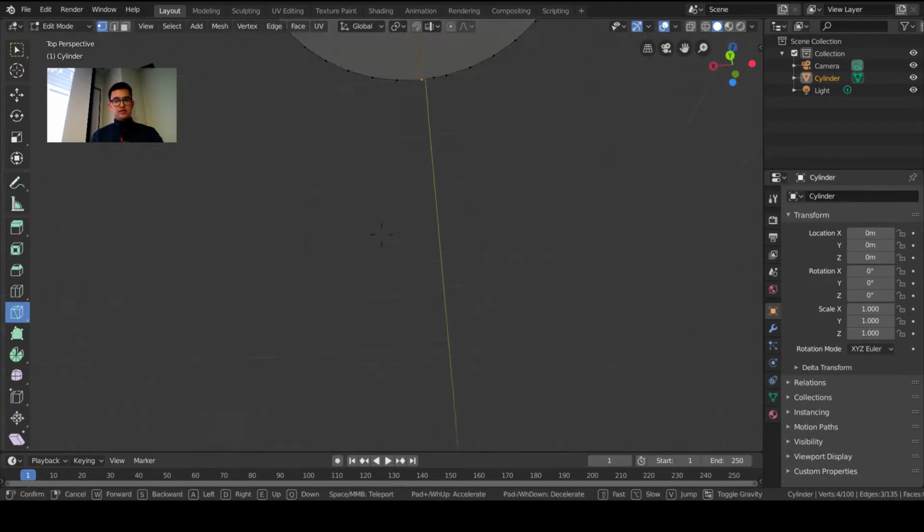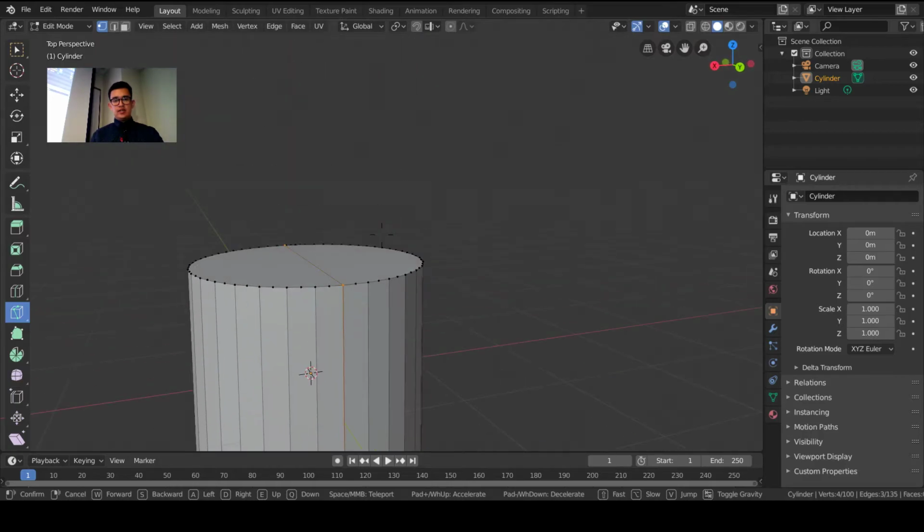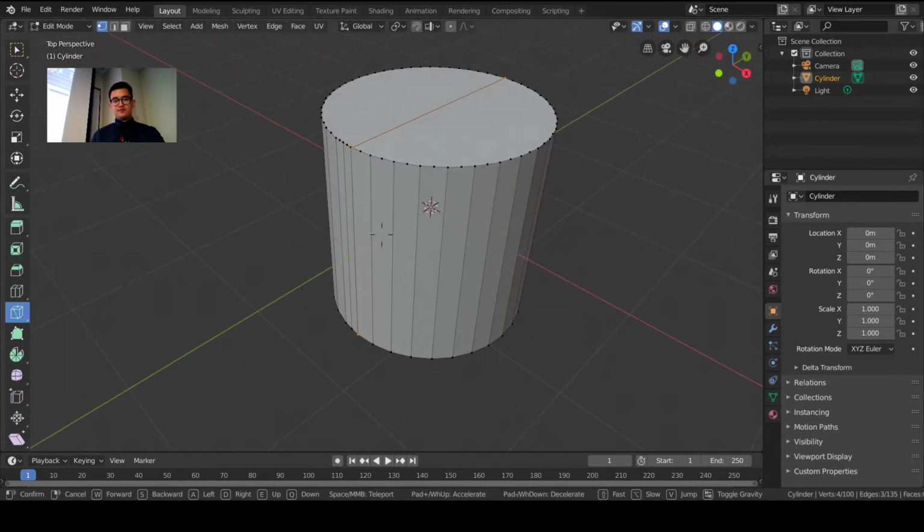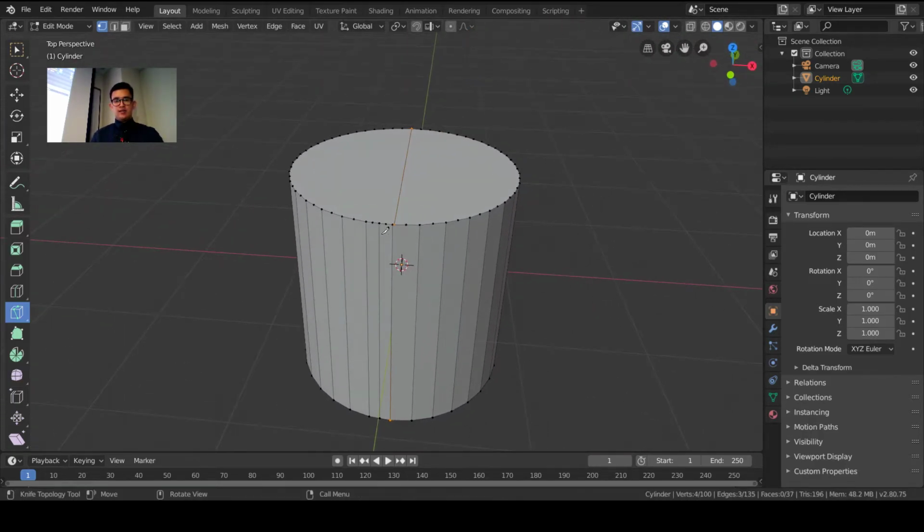So the next thing to do is learn about basic translation. For that, the hotkey to translate something you have selected is G, like goat, and we'll want to translate this left side. I haven't shown you how to select multiple objects yet. To do that, you just left click on something, and you can hold shift and click all of these.